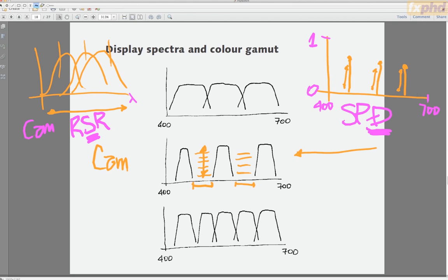Now, one way in a display to achieve wide gamut is to have more than 3 primaries. And we can see where we're headed here in the long term. The laser primaries allow us a huge gamut, but you have to use these very special light sources that only produce energy in a very limited portion of the spectrum.